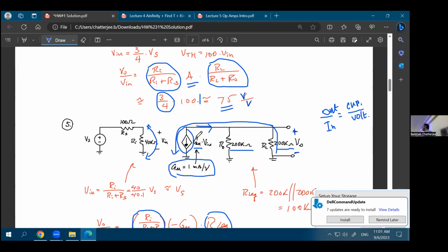And what's the meaning of the minus? It just means that whatever the phase at your input side, again, remember that this is an amplifier, and I have probably told this enough times, but I'll still repeat it, that an amplifier amplifies an AC voltage, not a DC voltage. So if you have an AC sine wave at the input side, let's say it looks like this. At the output side, what you will have is a 180-degree phase shifted version. That's all it means by the negative sign.